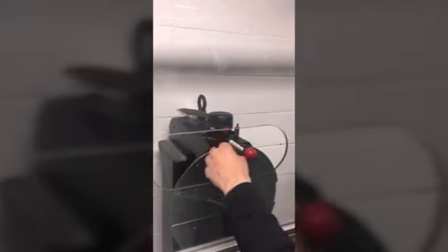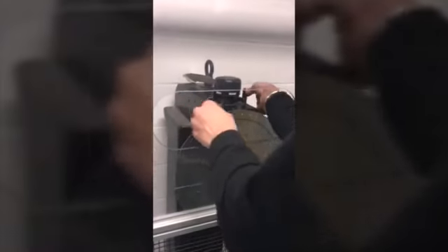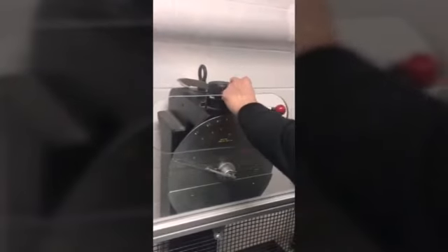After the experiment, once your pendulum has done its rotation, you can take your pin and take this to the brake position. After your pendulum stops, as you can see, our pendulum is at the stop position. Now you can take it back to the latch position. And in this way, we are done with our brass specimen.